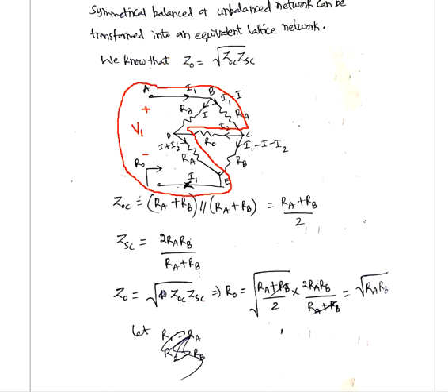So how many elements are there? We have RA, R0, RA. That means RB is eliminated from this path. This is how we have chosen that loop intentionally, so that we will have only R0 and RA, and directly we will get the ratio I1 by I2. Along with these three we have V1. And what is V1? V1 is nothing but R0 into I1, right?